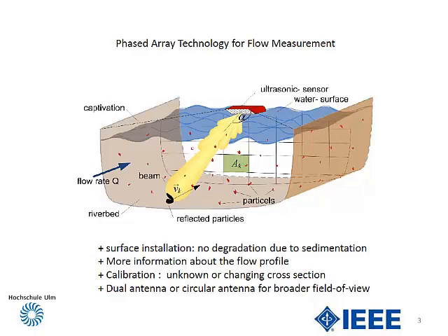Our proposal is now to apply a phased array for the flow measurement, because the natural shortcoming of the pencil beam solution, which is state of the art now, is that it doesn't collect enough information across the cross section of the open channel. We propose also an array which is swimming on the surface to avoid coverage with sludge, which is inevitable as time goes by.